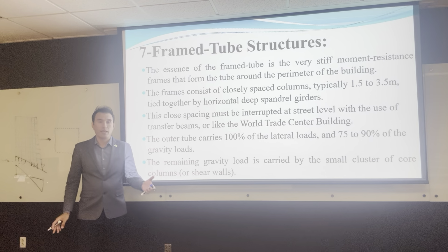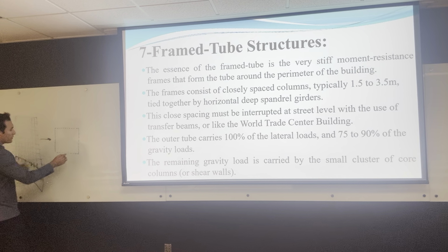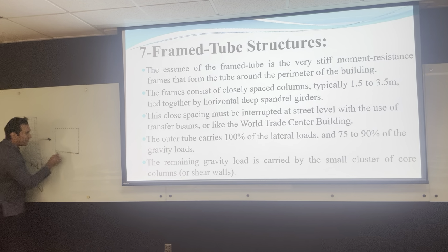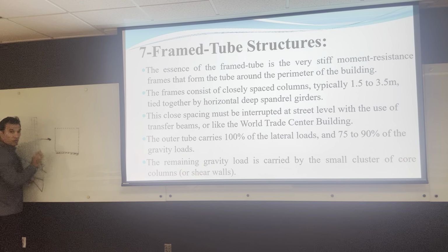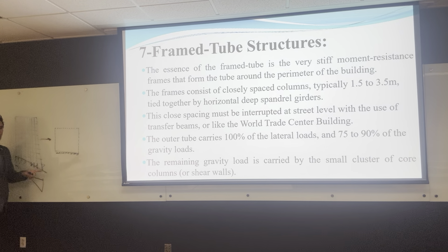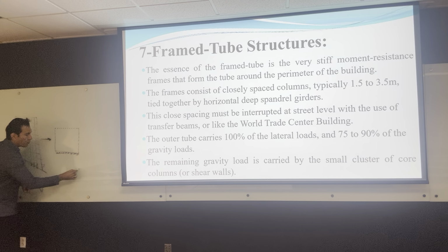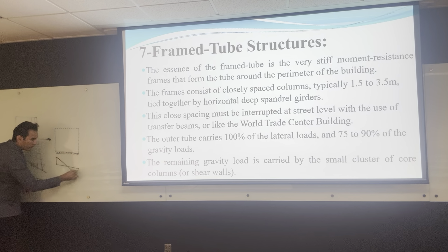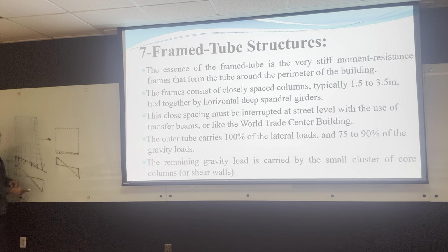It's called shear lag. So let's say a force hits that way, and we are saying that this is acting as a shear wall. If this is a really solid shear wall, the stress curve is gonna be something like this, a line, and this line is uniform until it comes here. But if this is not solid and has holes, voids like this, it doesn't behave like that.